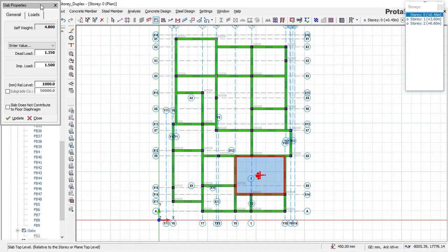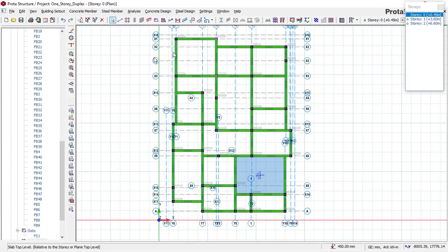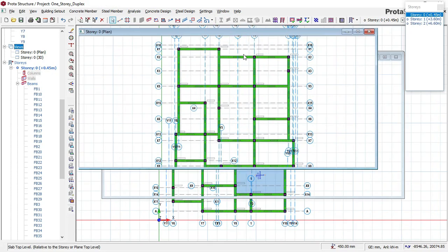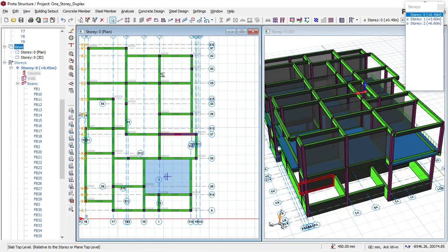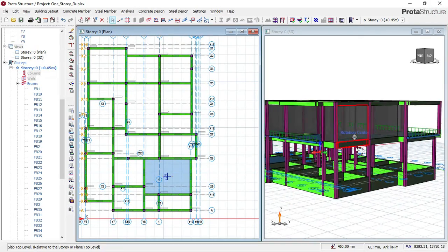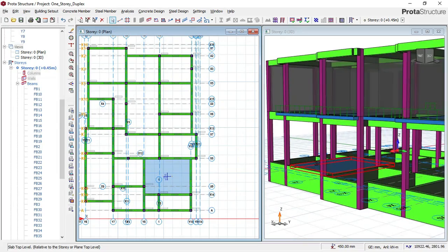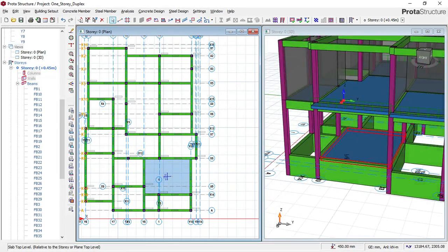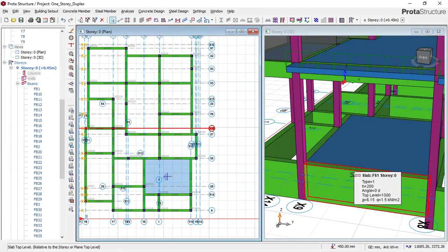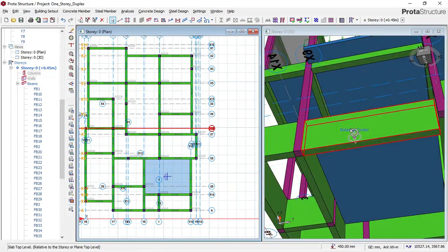And then I'll just close this up and check my 3D view to see what I have just done. I'll go all the way down to my 3D view. While on this view, I'll make my views vertical, where I can see the plan view and also the 3D view. Now you can see the first raft slab that we have inserted. The raft slab comes up because we put the relative level to be 1000, as you can see there.